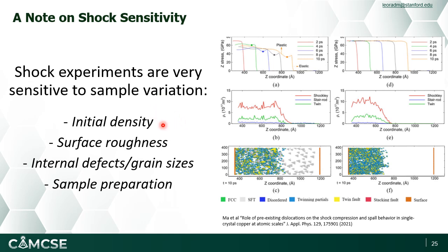We also, since we're looking at the transmission of pressure waves from one medium to another, at the very least when we generate our shock waves, but also when we observe them, are incredibly sensitive to things like surface roughness and even more subtle things like the glue layers and the thickness of those layers, as again, they create new interfaces that can create new impedances and new types of release pathways.